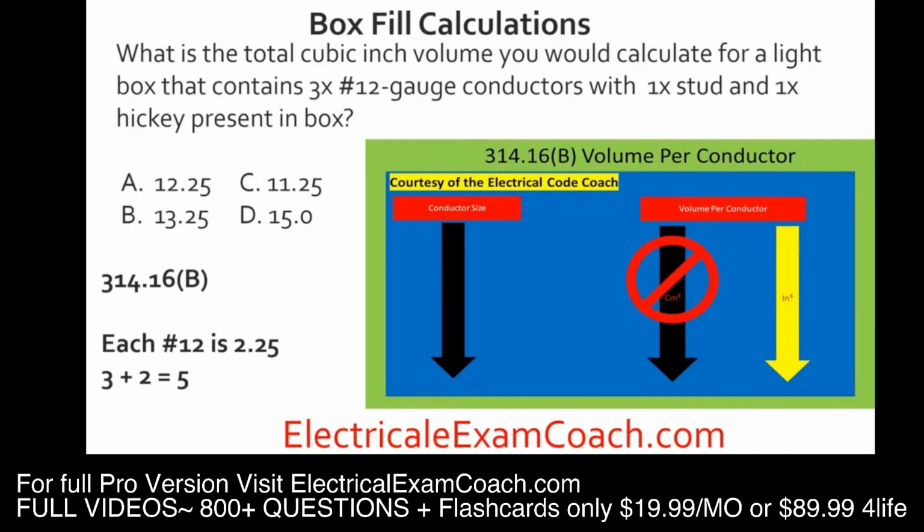In this case, we only have number 12s, so they're going to be grouped with the 12s. So that lets us know that we have a total of 5 number 12s. That's what I meant by we're converting everything back to conductors, and then we can do our multiplication. We take those 5 number 12s, multiply it by the cubic inch volume for 12, and we end up with 11.25 cubic inches, and we would select C.